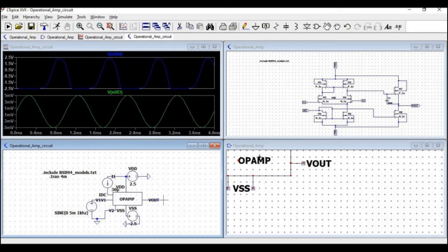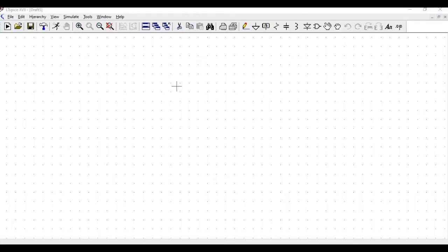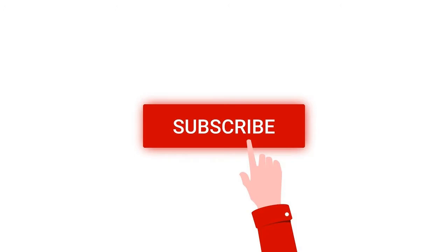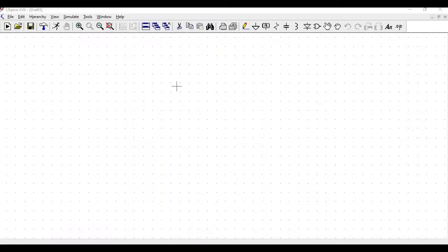Welcome to this channel. In this tutorial, we will simulate an operational amplifier using MOSFET and LTspice tools. Let us start the circuit design of the operational amplifier. Click on New Schematic.